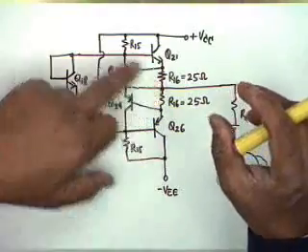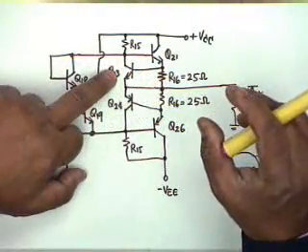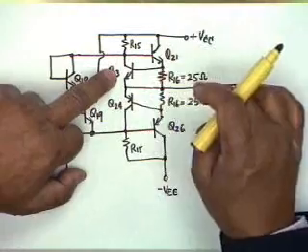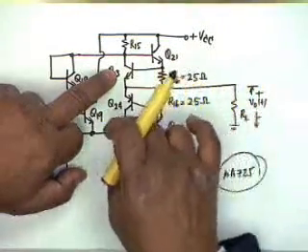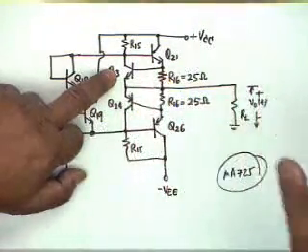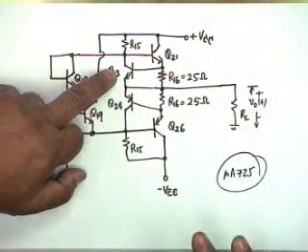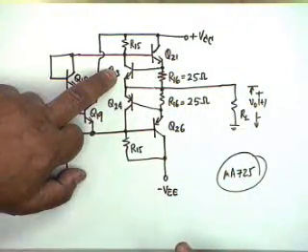Saturation means charge accumulation, and the charge requires a long time to come out of saturation. So this resistance and Q23, the two together, the function for R16 and Q24 is exactly the same during the negative half cycle of the input voltage. So it suffices to consider the positive half cycle.